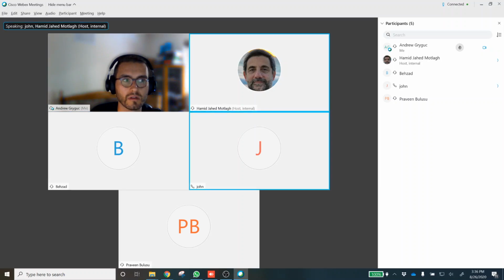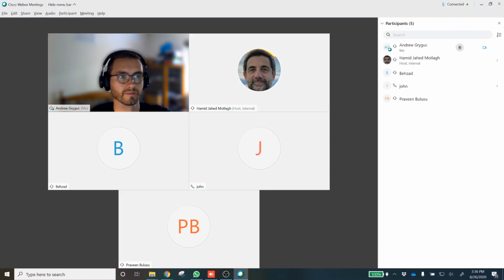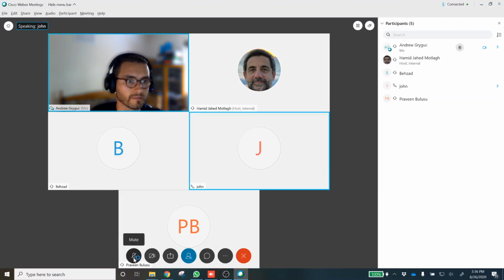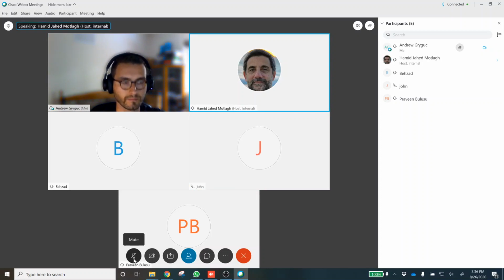It won't be from a vehicle, so it will be a fresh bolt, so it won't have any preload or anything in it. Okay, understood. It typically goes from an arm to the subframe. That is the bigger size bolt. But for fatigue testing, you would like to have that mean load on it when we are doing cyclic tests, right?